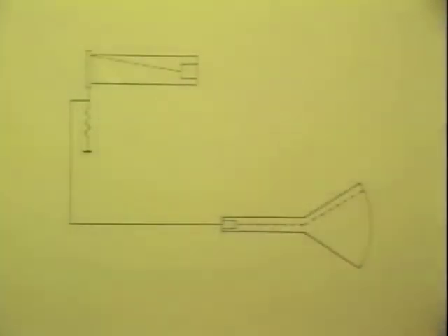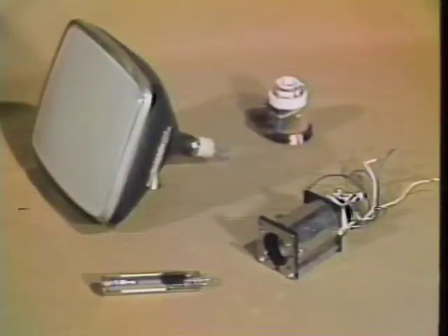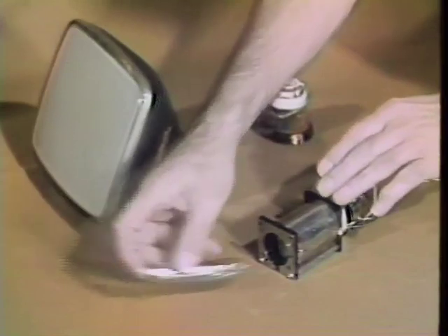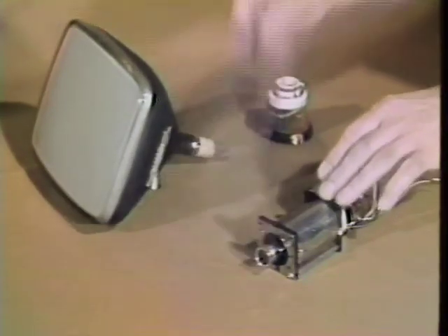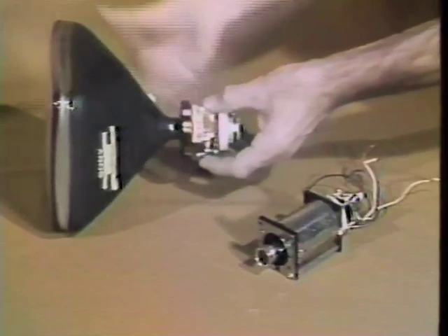So now, let us examine what makes the beam move and scan the screen. The beams in the camera and monitor tubes are moved horizontally and vertically by magnetic fields produced by coils around the neck of the tubes. One set of coils is used for horizontal movement, another set is used for vertical movement. The magnetic fields are produced by currents in the coils, and both fields and currents are varied by applying voltages to the coils. The coils are wound in yokes, as seen here.